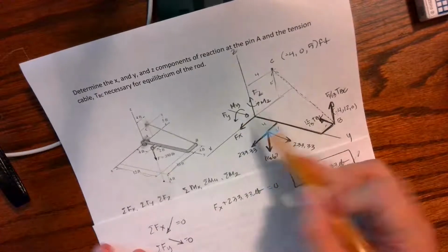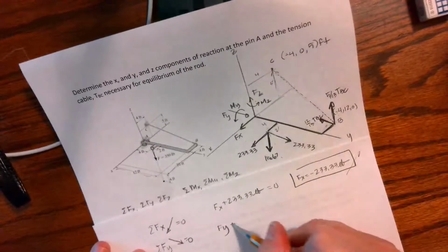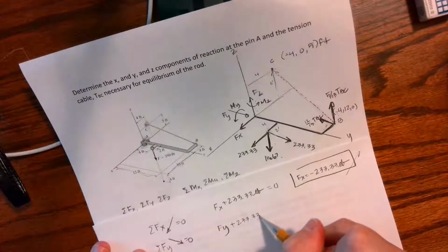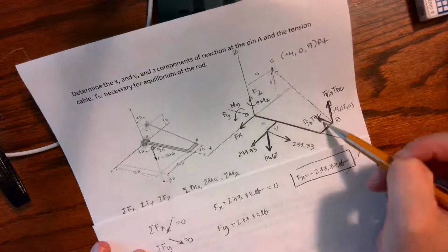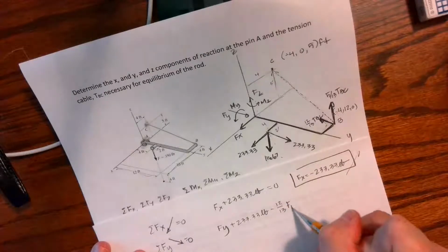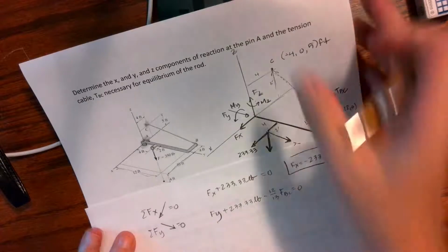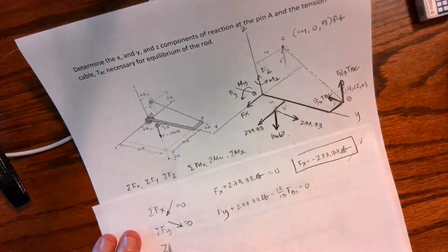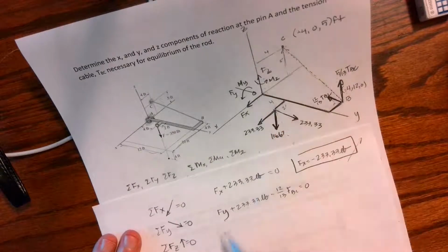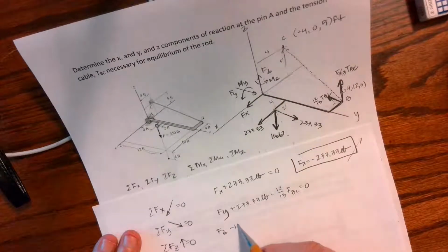We do develop a force in the y direction, positive. We're going to come around here. We do have an applied force, 233.33 pounds. We're going to come around here. We do develop a resisting force, minus 12/13 FBC equals 0. So this one's not as helpful. I still have two unknowns. Let's sum forces in the z direction. Up is positive. We develop a force in the z direction. We're going to come around here. We have a negative 116.67 pounds applied.